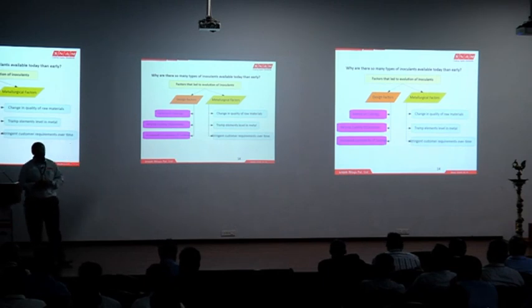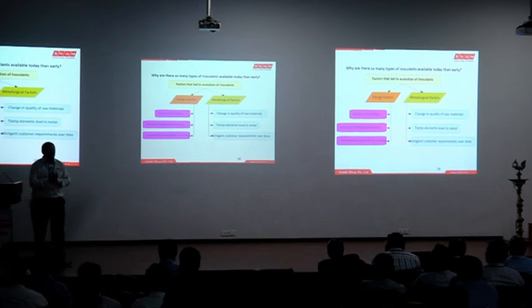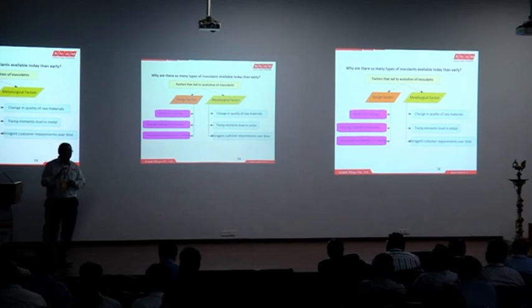So there are a lot of factors involved in altering the charge mix to get the same quality. But the actual problem is, though you may be able to get the same chemical composition as we have been getting with a different charge mix, when you add different ingredients and make a casting, the property or the functionality of the casting can have a small variation between the one made with one charge mix and the other with a different charge mix.